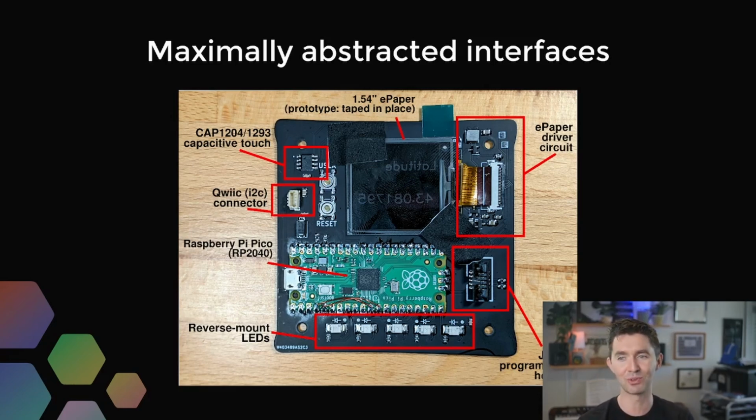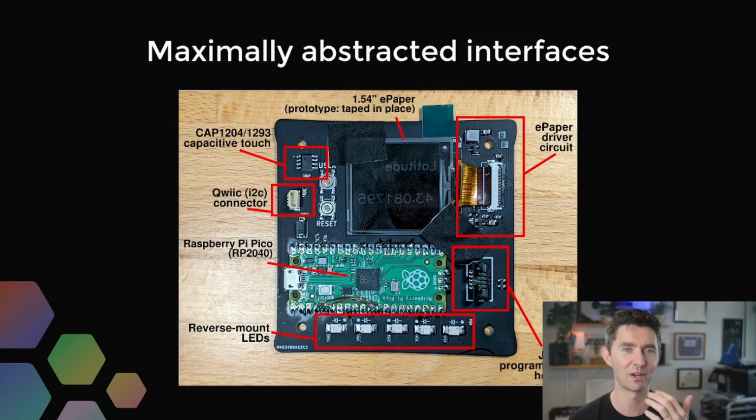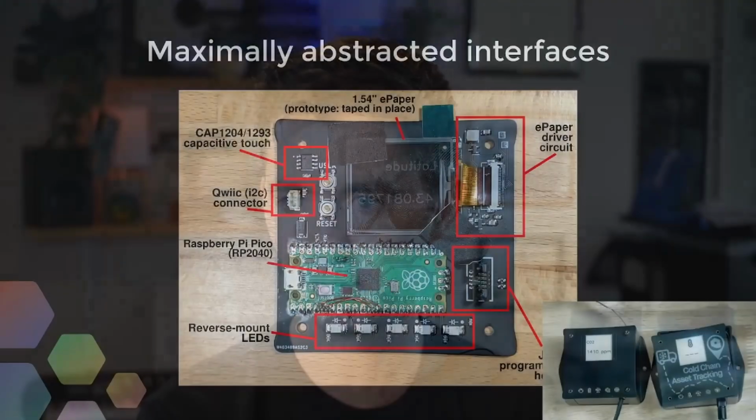But it's also got an RP2040, which is like a board that I would never use in production. It's got the Pico rather, which has an RP2040 on it. I wouldn't put a Pico in production, right? But I might put an RP2040, or I would go chip down at least. But that worked out for me, right? This is another kind of dev board way of proving out this idea and interfacing with it, and making sure that we can make it maximally flexible. Again, it might not be something that you're thinking about here, but it was very, very useful for my testing. Let's see if I can find the camera for it.